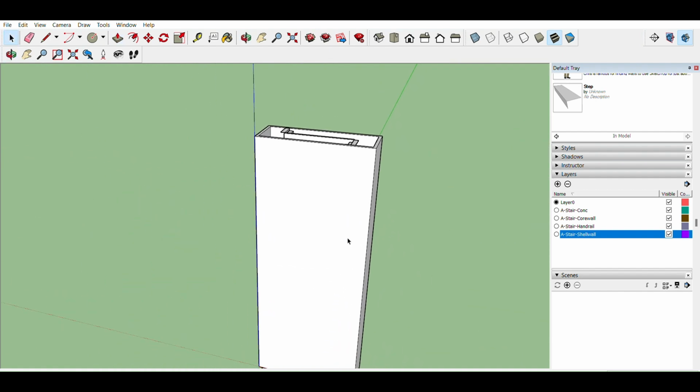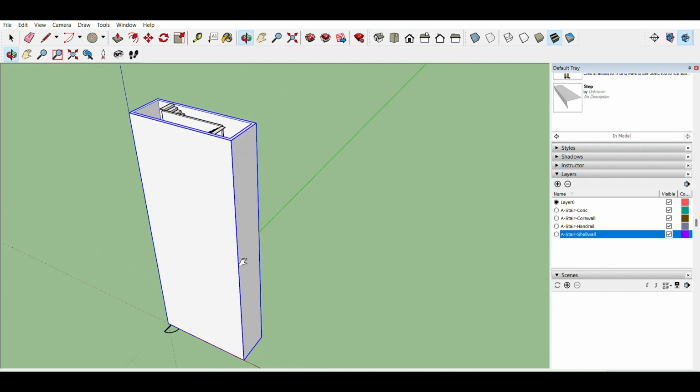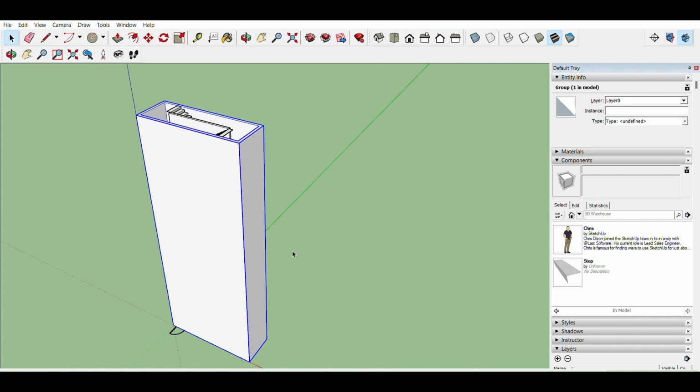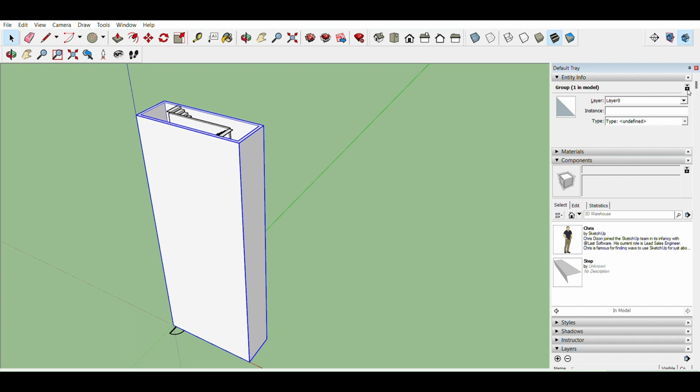There, and obviously it's going to be higher to the next floor. Kind of want that to be in a group. Okay, so it wasn't in a group, which means that all of this geometry that I selected, oh look, it's all over the place. So let's put this back to layer 0, take the group itself, and change it to a stair shell wall.